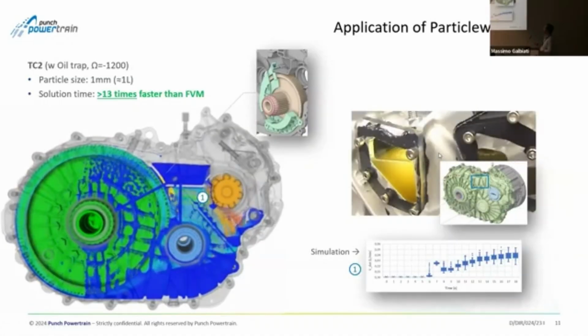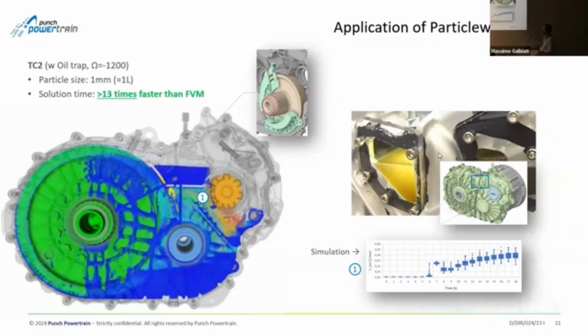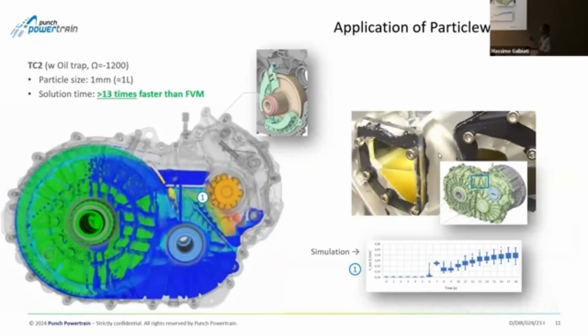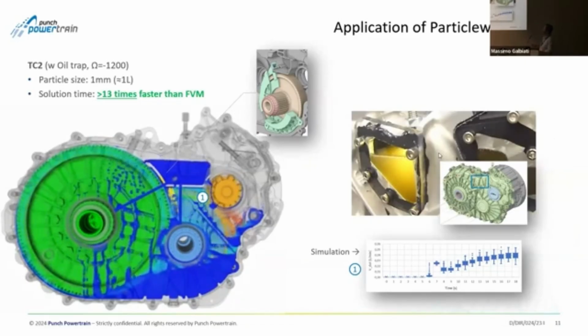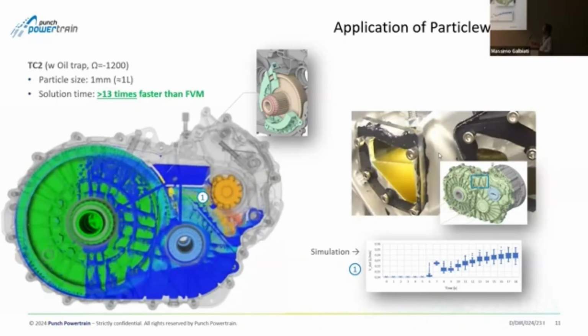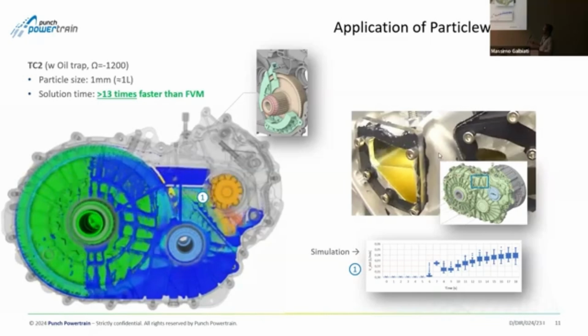Maybe I didn't explain the detail, but in principle, the challenge in this motor, in this design, was that our client, or even ourselves sometimes, want to test specific things like the backward driving condition, which is the case here. For the differential, for example, in the normal design of this motor, it goes in the other direction, and it splashes the oil into the reservoir on the differential when the car is driving from left to right.